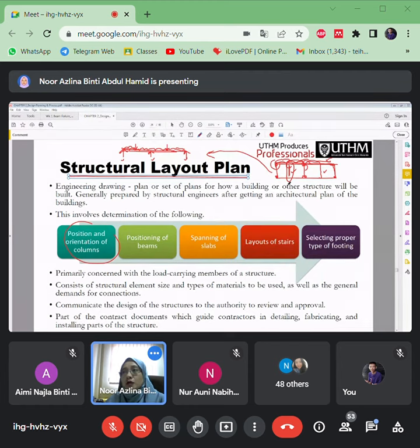But once you do the analysis, if it is not safe, the load here is too high and the moment is too high here. If the moment is too high, we have to provide a lot of reinforcement. To provide a lot of reinforcement, the beam is too small and cannot fit the reinforcement and everything. So that means we have to increase the support.